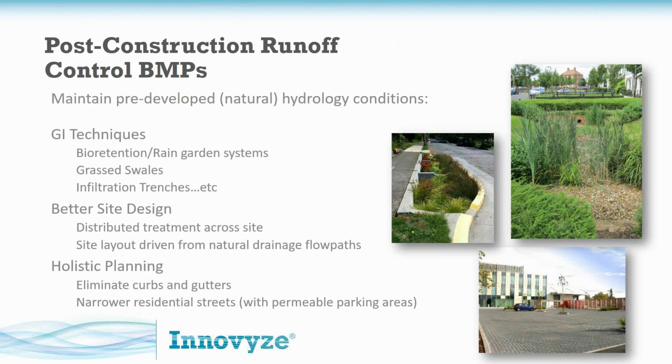So if we can narrow and limit those streets, the imperviousness, okay, well, from a design point of view, we'll be asked to treat a lot less, right? Usually we're trying, and we'll talk about this, but we're trying to mitigate impervious runoff. Well, obviously reducing what imperviousness there is would be a big help.